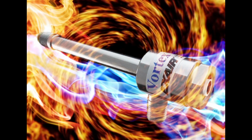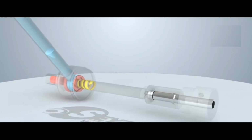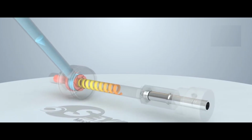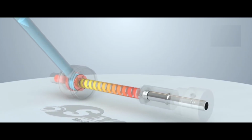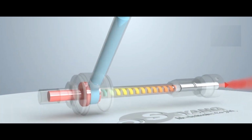What if a single device could turn compressed air into both hot air and cold air at the same time? That is exactly what the Vortex tube, more specifically the Ranque-Hilsch Vortex tube, is able to do. A Vortex tube is a simple mechanical device that uses compressed gas, usually air, to separate a single inlet flow into two outlet streams, one hot and one cold.